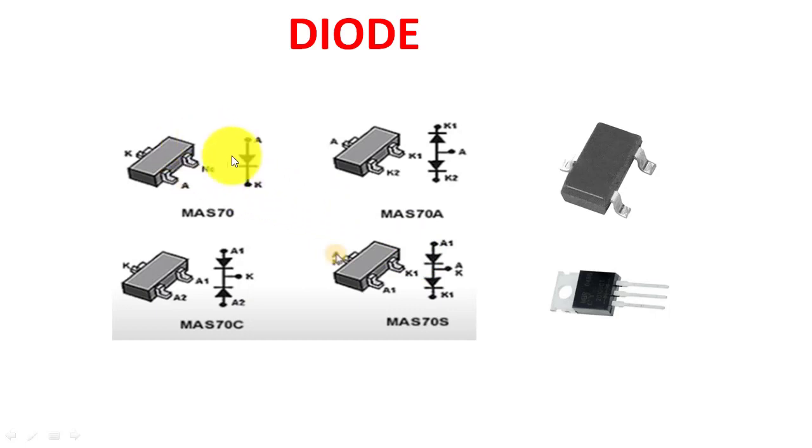There are possibilities, how they are used in various ways. You can see that on the upper side leg, this is the cathode, and the down leg, the left side pin, is the anode. Anode to cathode, okay, and the other pin, the right side pin, is NC, not connected, okay. So we'll have to measure like that.